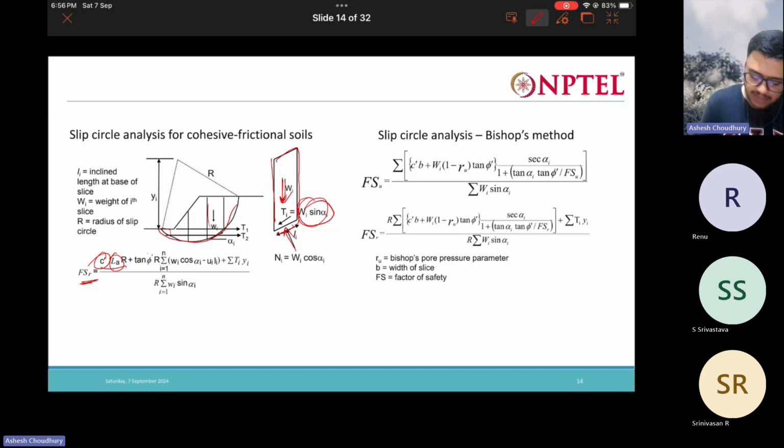The normal force is W_i cos alpha_i minus U_i, where U_i comes from the pore water pressure, summed over all the wedges, times R.